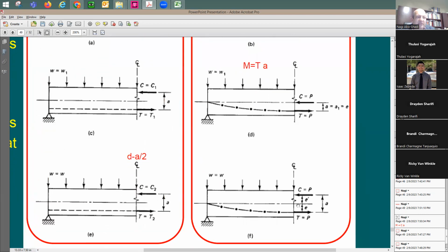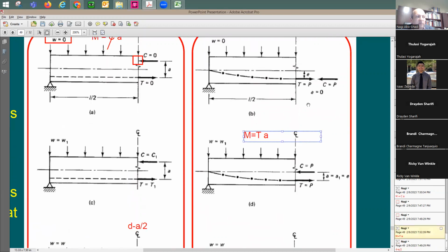When you have the maximum moment, right? Once you start to apply lots of moment, now you are at the surface level. Once you are at the surface level, what's going to happen? This compression force is going to be jumping up more. When this goes up, it means the moment arm is going to increase. So in this case here, the moment arm is going to be equal to 0 because the two forces are going to be aligned with each other.